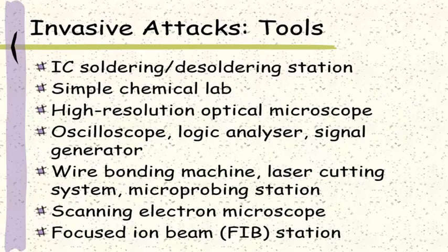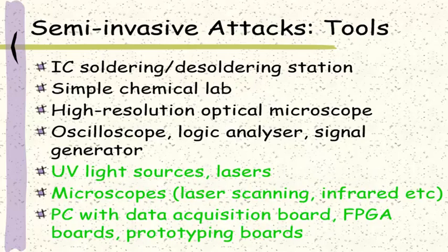Next, in the semi-invasive attack, the attackers also need to depackage the silicon to open up the chip. However, they do not need to create contacts with any internal signals. Therefore, the expensive micro-probing station and other equipment may not be required for semi-invasive attacks. Instead, the attackers will have to use other equipment to launch various semi-invasive attacks.